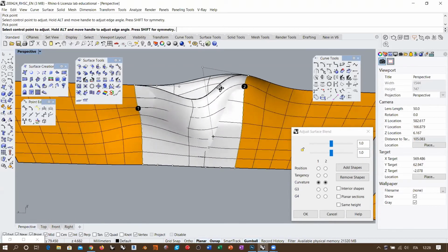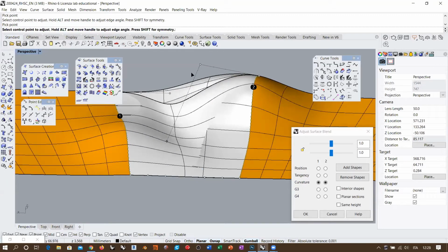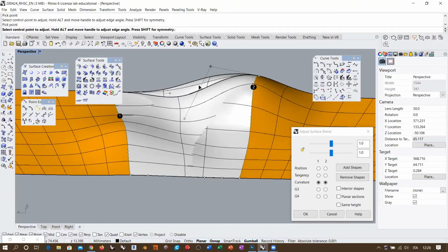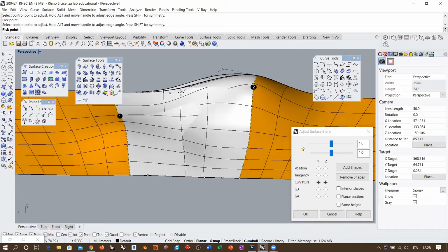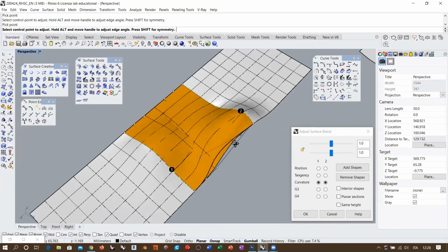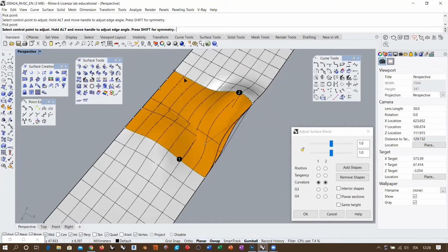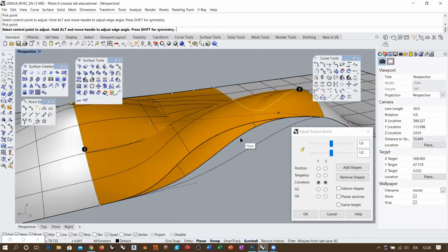So what we are doing here is creating a new connection surface with curvature continuity, exactly like the first one, but with a totally different shape, even if we are maintaining the same level of continuity, okay? So it is for this reason, because the sweep to rail has to work all along the rails, that you cannot rely simply on the topology of the cross sections, okay?